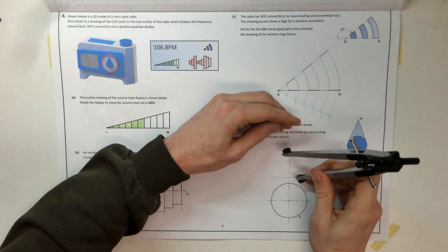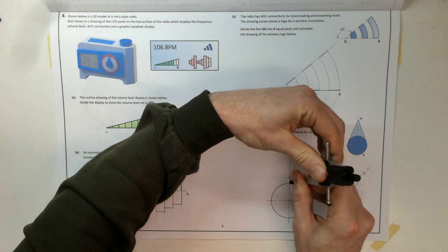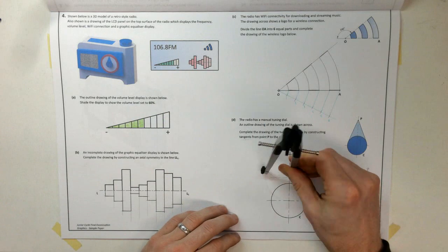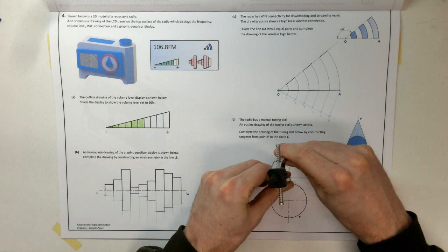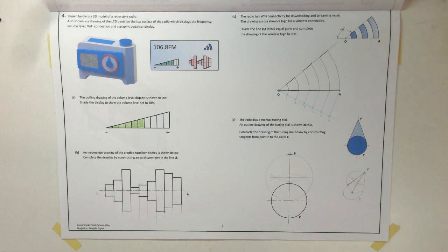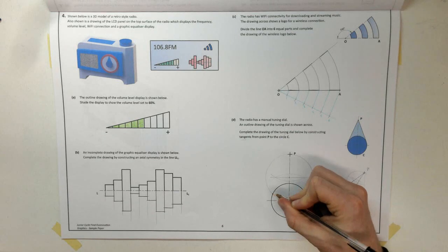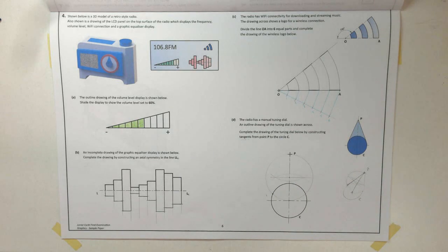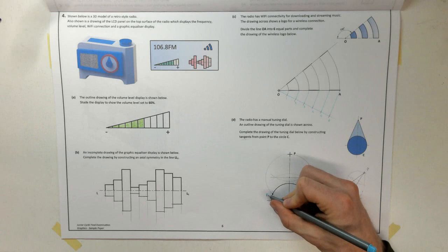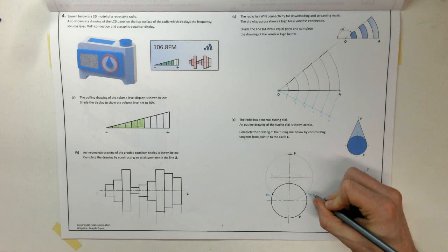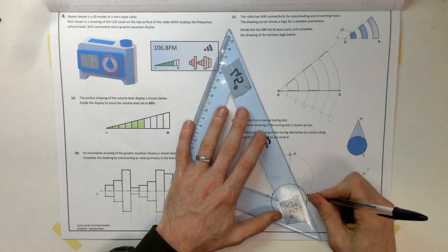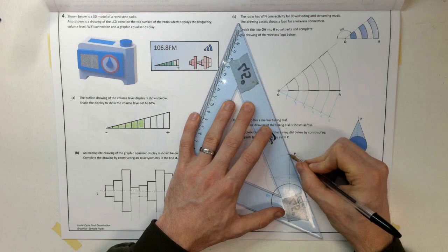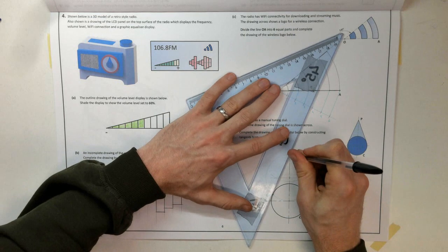I'm now going to draw a semicircle. Actually, it'll be a full circle because I'm looking for two tangents. So there's my circle drawn. So right here, that's my point of contact, POC. Actually, I'll use a colour for that. POC. Over here, my POC. Okay, so I can now draw my tangent from P to the POC. That's tangent 1, and that is tangent 2.